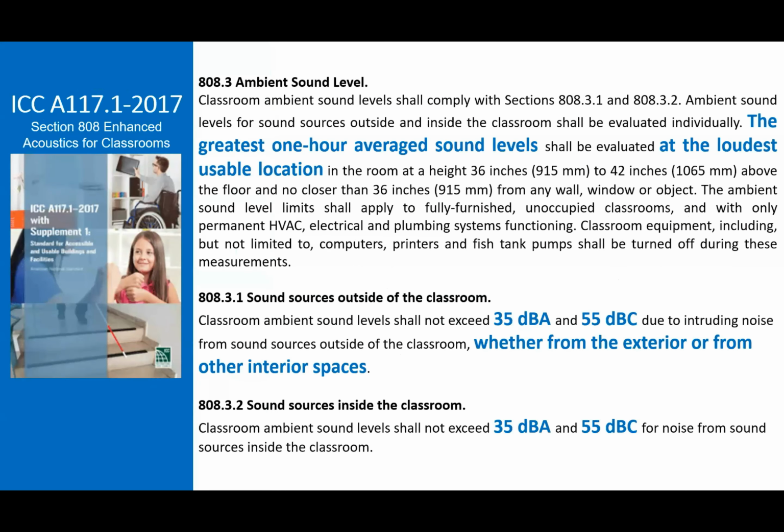So where the enhanced classroom acoustics requirements get a bit nuanced is in this next section, where we have this 808.3 ambient sound level requirement. Within this requirement, it says that the greatest 1 hour average sound level shall be evaluated at the loudest usable location.